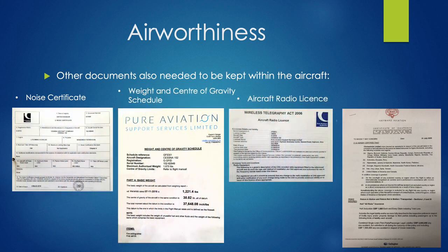So here's a list of a couple of other documents that need to be carried within the aircraft. So legally, we need to have a noise certificate, a weight and center of gravity schedule, so they'll weigh the aircraft and see where the center of gravity lies, so we can work out the mass and balance for when we add fuel and other cargo. An aircraft radio license to say that the radio is serviceable and of the correct kind, and also aircraft insurance details. And we need to have all these documents inside the aircraft.